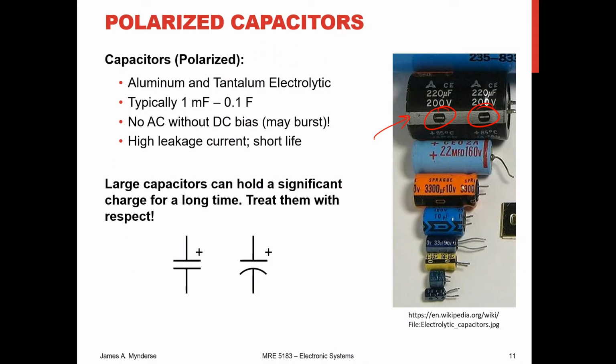These do tend to have a shorter life. You will see that on the ends here, not visible in these pictures, there will often be some sort of arrangement like this with some marks, and that allows these things to clearly fail. When the dielectric in there is getting older, it'll tend to expand a little bit, and you'll see a little bit of a bulge, and that bulge tells you that the capacitor is no longer good.